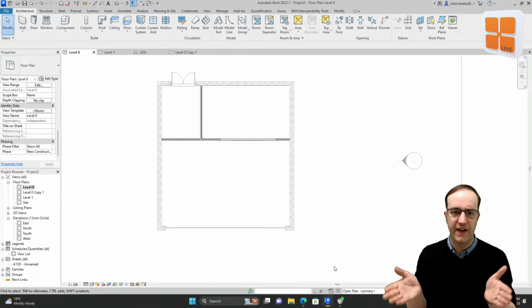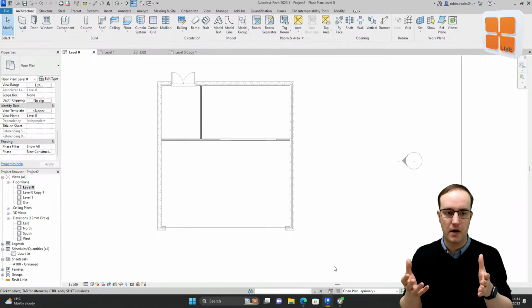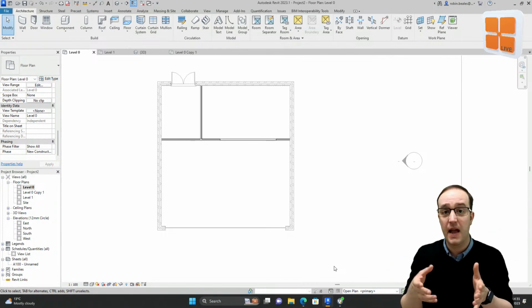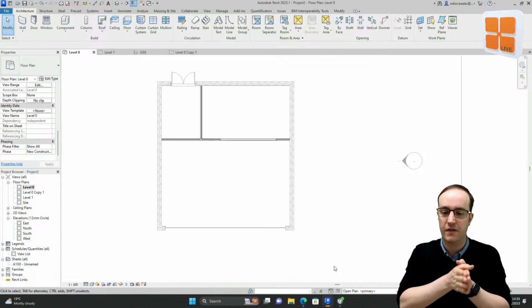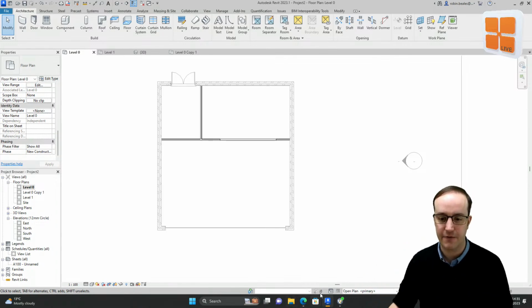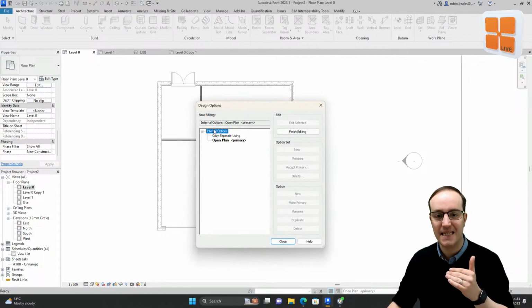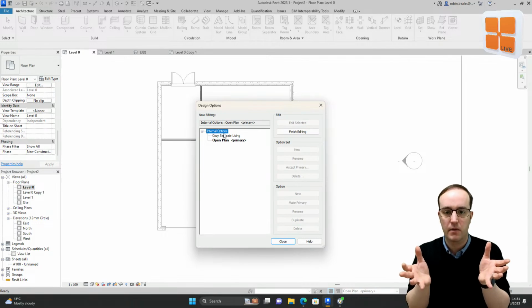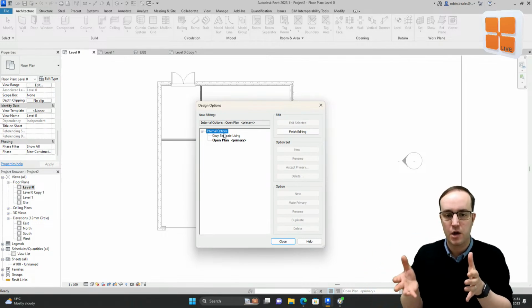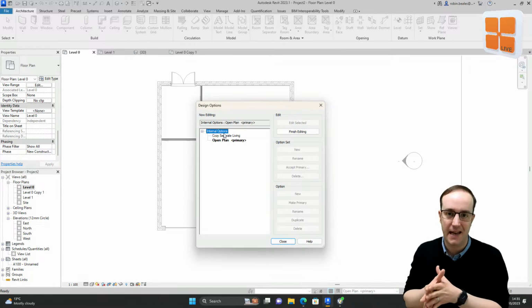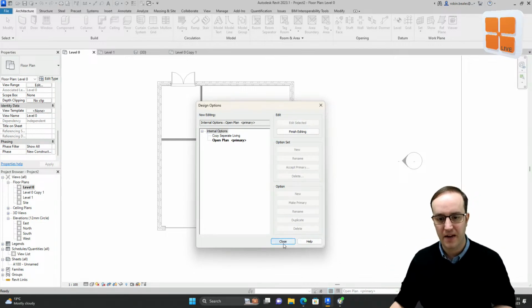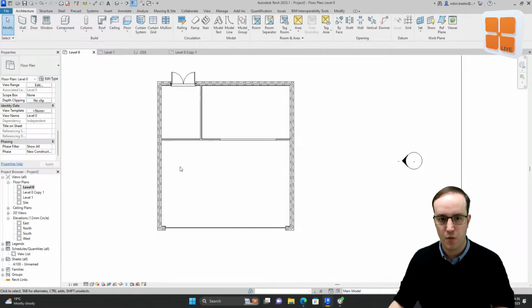If you're showing phases, think about the fact that I've got my views, 3D, 2D, renders, whatever they might be, Enscape walkthrough, they are linked to whatever option is active. I can have as many different option sets as I want. We have the main model, it's never editable outside of the main model environment. You can only edit the bits within your particular option set. You can add and remove as necessary from those, okay? But you need to go back to the main model if you wanted to make any changes from here, okay?